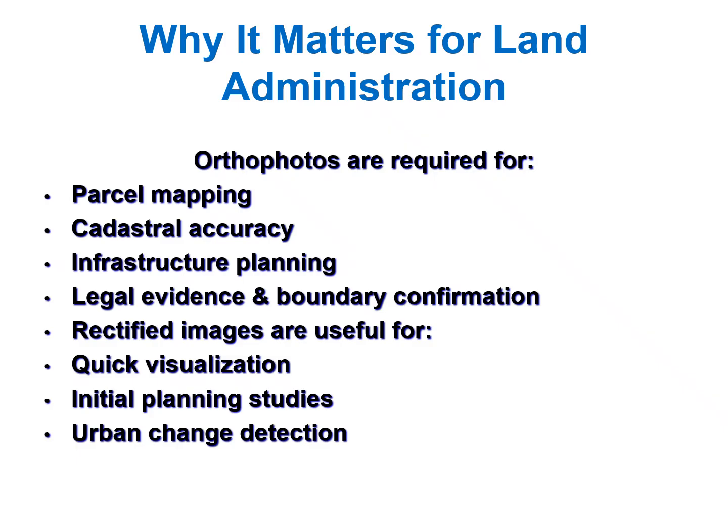Why it matters for land administration. Orthophotos are required for parcel mapping, cadastral accuracy, infrastructure planning, legal evidence, and boundary confirmation. Rectified images are useful for quick visualization, initial planning studies, and urban change detection.